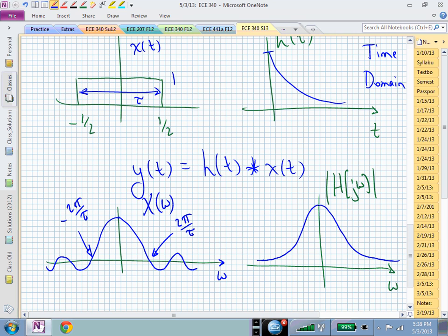And you might want to know, how is this frequency here related to the frequency content in your pulse? And if you are now having a very narrow bandwidth in terms of how many frequencies are passed in your system, in your communications channel, or in your filter, then that's going to be related to this frequency content in your input signal x of t.